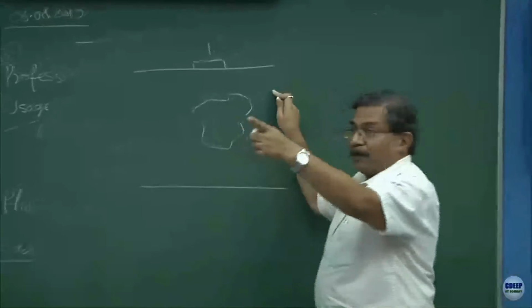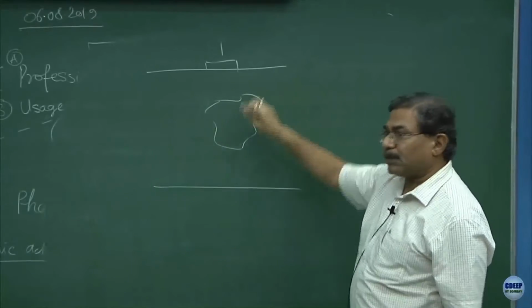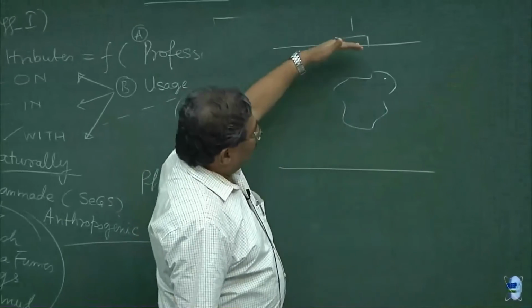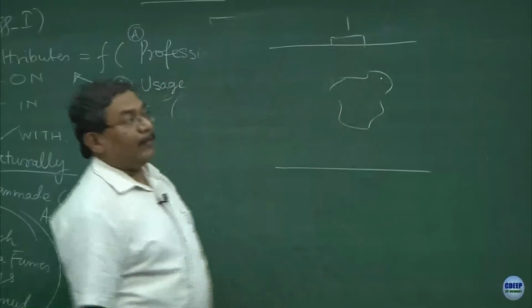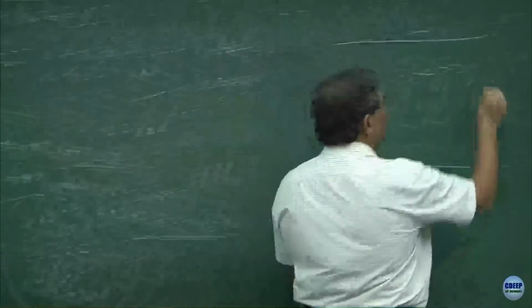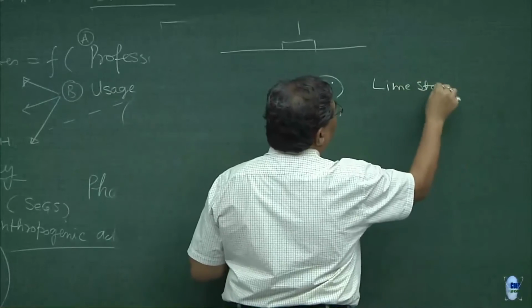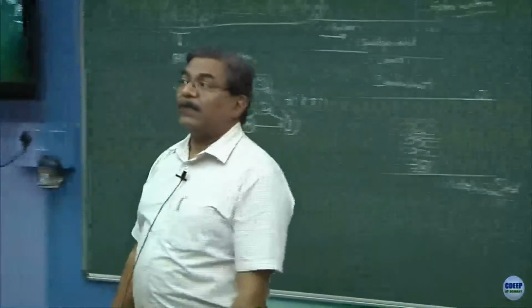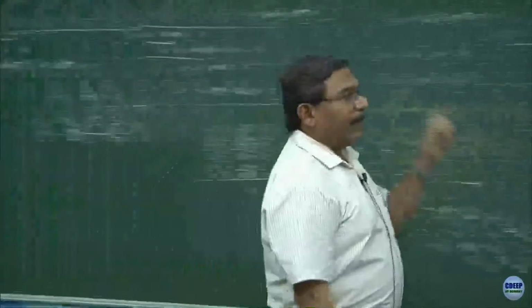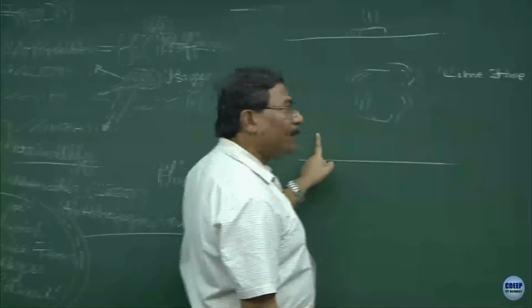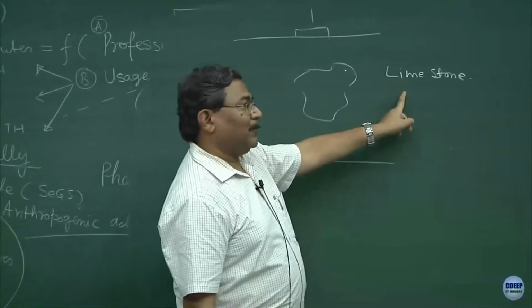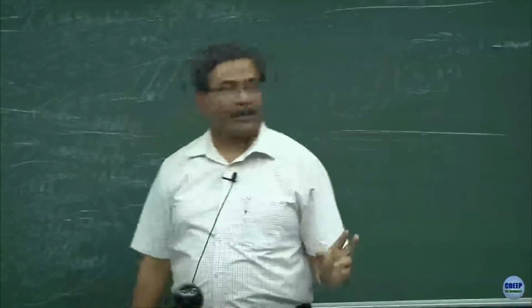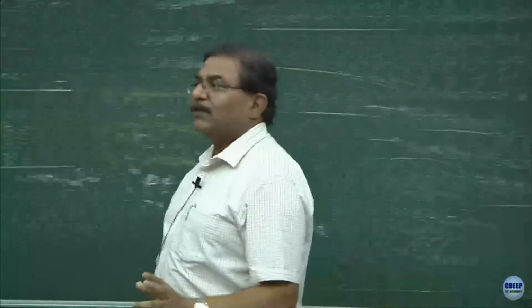Look at this, another example of the chemical process. Coming back to the question which you asked, these types of subsurface deposits are very notorious. Mostly they are limestone, and they are sitting in the coastal areas. Clear? What does seawater have to do with this? Now, this seawater ingresses into the foundations or the strata, and has a tendency to eat up the limestone and create cavities under a very specific condition of pressure and temperature and humidity. This is what is known as lime dissolution.